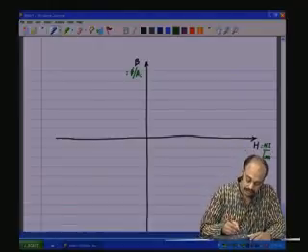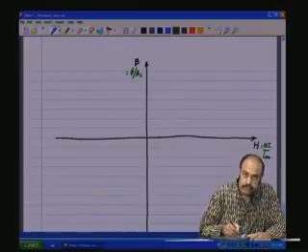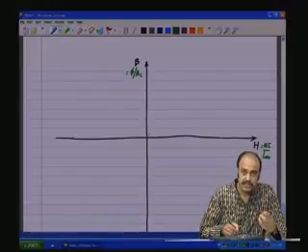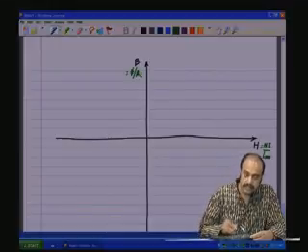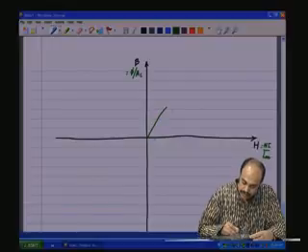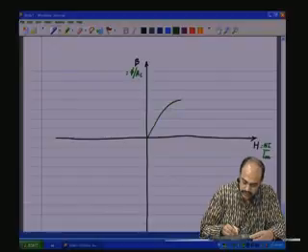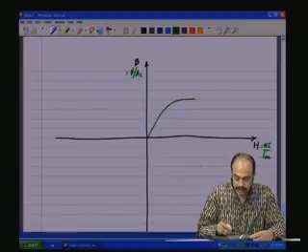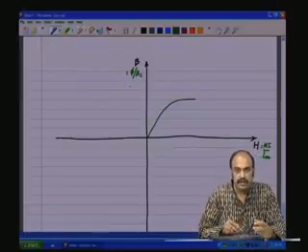So in actuality, you will see that, let us say we start with a virgin specimen, a new specimen. As the field intensity increases, as the magnetomotive force increases, the flux in the core will increase. Flux keeps on increasing as you increase the magnetomotive force in the x direction. But you see that it loses its linearity and gradually it starts to saturate. So beyond a particular value of magnetic field intensity, the flux in the core will not increase any further.